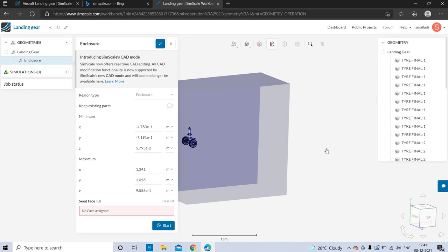The standard dimensions of the domain considered for analysis are: the inlet wall distance from the geometry is 10 times the length of the geometry, the outlet wall distance is 15 times or 20 times the length of the geometry, and the other sides of the domain are 10 times the length of the geometry.